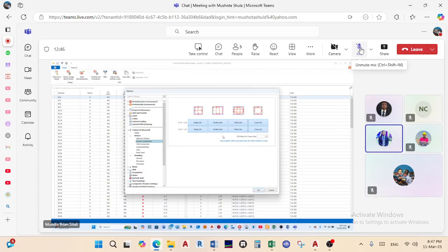I was basically commanding how the rebar should sit. If I had these options and clicked as it was, I was only going to confine my design to having one ring around and then those tie links, column ties.